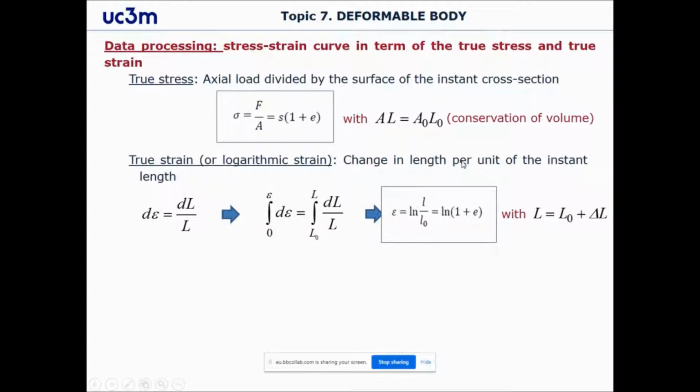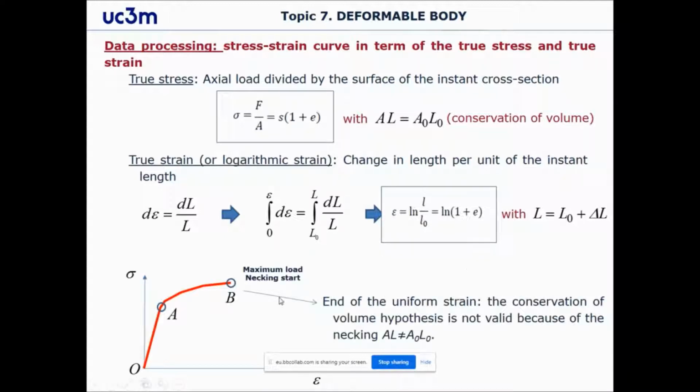But at the same time, using the same conservation of volume, we can arrive at this expression that is very useful at the end, in which the true strain is given by the natural logarithm of 1 plus the engineering strain, right? So those are the two equations that we're going to use. And here we'll also find a definitely similar behavior. I would like to start by